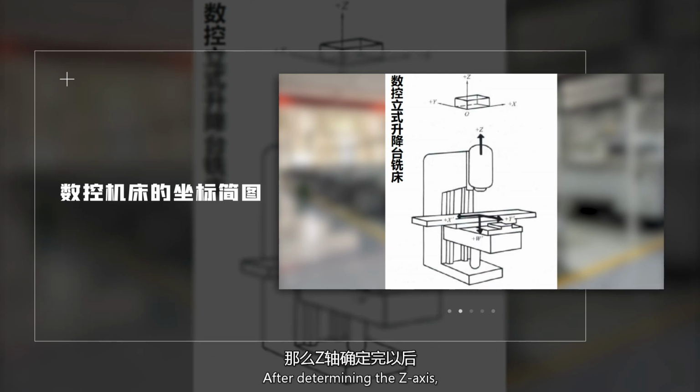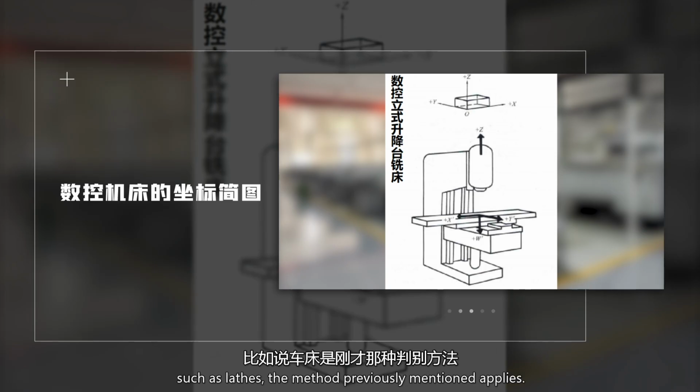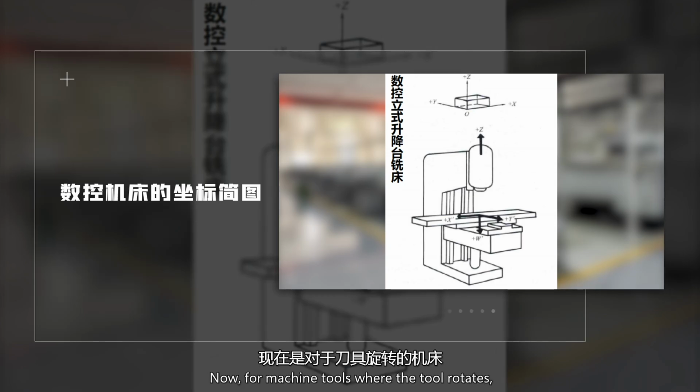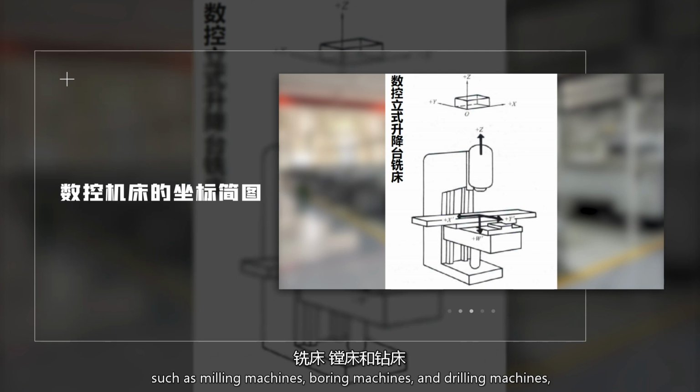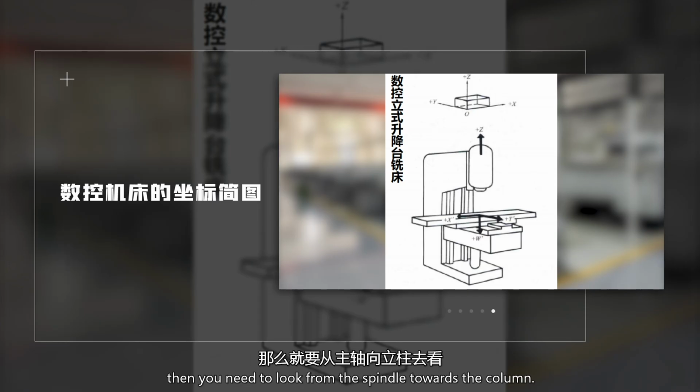After determining the z-axis, the next step is to determine the x-axis. For machine tools where the workpiece rotates, such as lathes, the rule previously mentioned applies. Now, for machine tools where the tool rotates, such as milling machines, boring machines, and drilling machines, if the spindle is vertical, then you need to look from the spindle towards the column.